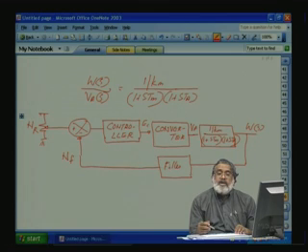So what happens? Full voltage is applied to the machine. So heavy current will flow initially. So sometimes, depending on the applied voltage, the current can be beyond the rating of the machine. Till the speed picks up, the current will be flowing and the winding will get heated up, and the machine can get damaged. So here the problem is current is not controlled.